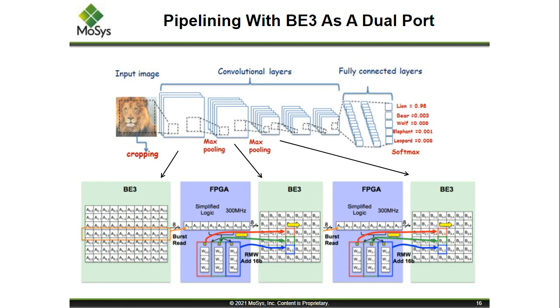And in these devices, because the ports are separated, you can have one port talking to one host and a separate port talking to a different host, and it even allows that to happen at different frequencies. So if one of your hosts has to run at a much higher frequency because it's doing other calculations, the device allows that kind of clock domain crossing to occur within itself.